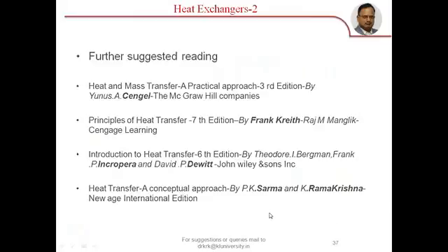So this is the end of the chapter on heat exchangers, and we have seen some concept questions and we have revised. Fundamentally, the heat exchangers chapter is simpler than any other. You have to remember only the basic energy balance equations along with one heat transfer equation, U A LMTD. If you cannot calculate LMTD, then you have to go for the effectiveness and number of transfer units method, where somehow you have to find the effectiveness, which involves only 3 temperatures. From that, the third temperature can be determined, and so on. It continues.